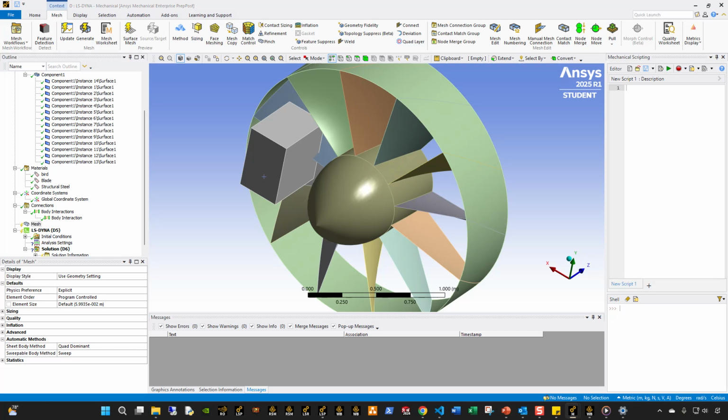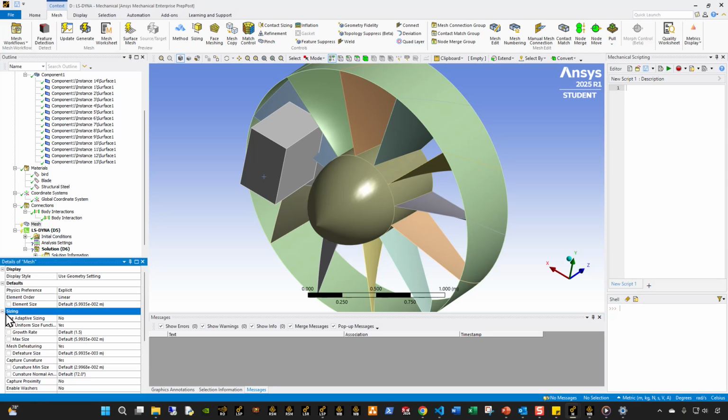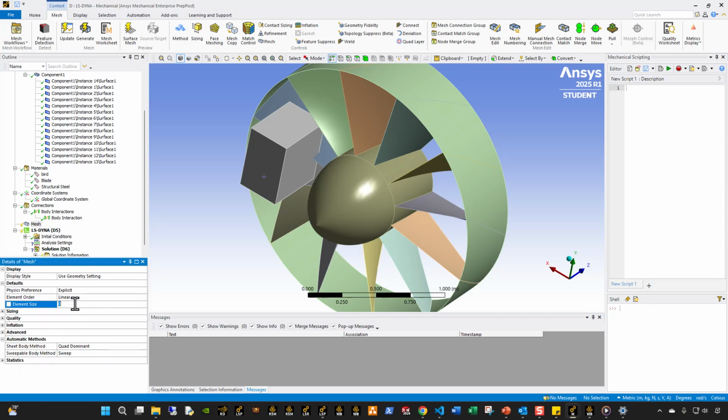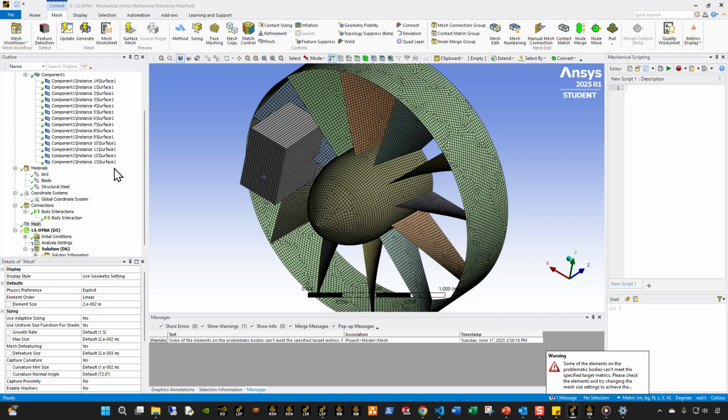The mesh that we created is very simple. I'm just going to define the size. I think something like 2 to the -2 meter, so it's about 20 millimeters, right? And if I were to mesh this, it would just give me a 20 millimeter uniform mesh across the board. And I'm not even defining the section and everything. Most of this is relatively simple. The section card for the ALE material is going to be automatically defined when we write out the input file. So everything else is basically standard, right?